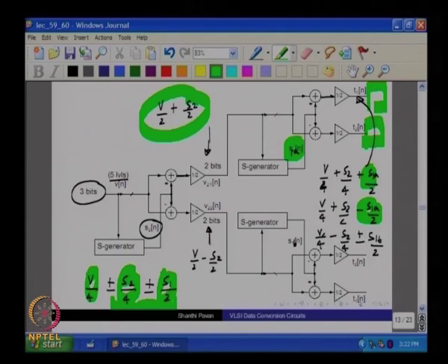It will be exactly the same spectrum as V, because at every layer of hierarchy we have ensured that the sum of the split sequences is exactly the same as the input, which means the sum of all the thermometer drive waveforms at any instant of time will be exactly the same as V at that instant of time.